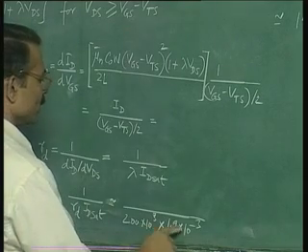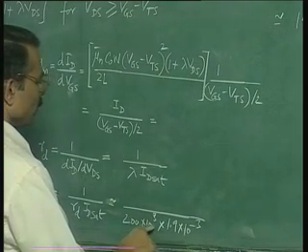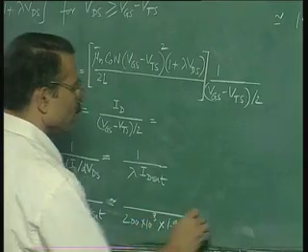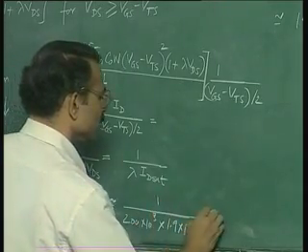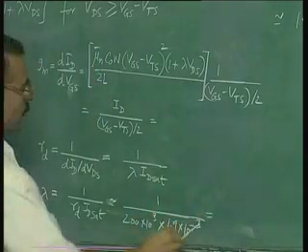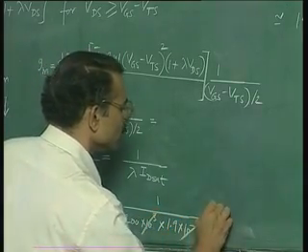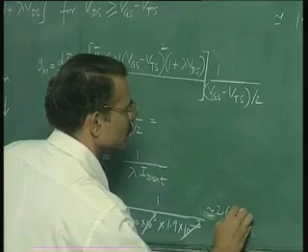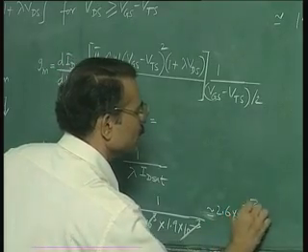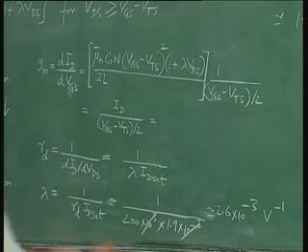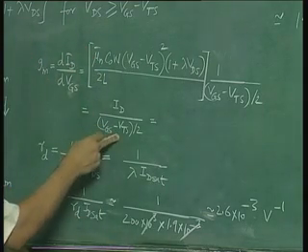So obviously the unit is kilo ohm into milliamperes is 1 by volt. So this result is 1 by 380, which will be about 2.6 into 10 power minus 3 per volt. Okay, so this is your lambda. Now finally we can evaluate the GM.